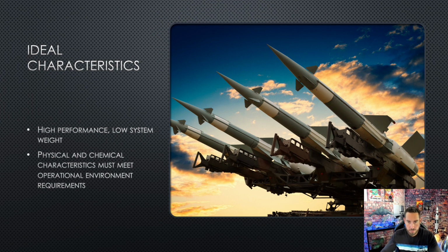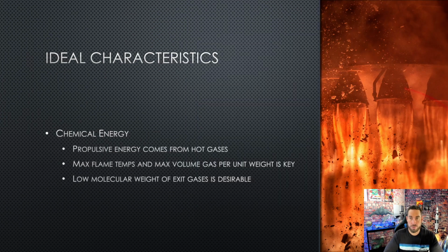Also, when you're looking at terrestrial use in missiles, you don't want to use something that's cryogenic, because when they're using these surface-to-air missiles, they're not fueling them before they're launched. If you have an enemy jet coming into your airspace, getting ready to blow you up, and you need to blow them up first, you don't have time to go out and fuel the rocket. You have to have storable fuels that are already loaded and ready to go. Using a cryogenic in that type of setting is not going to be feasible. So you would need something that's storable with a wide range of temperature efficacy. Anyway, that's something to take into mind when developing fuels.